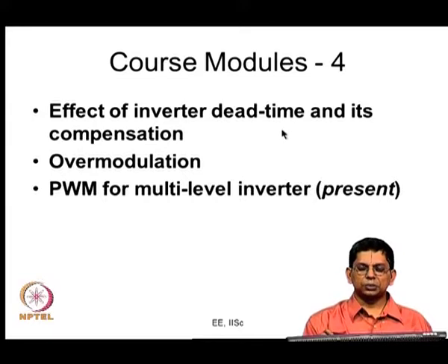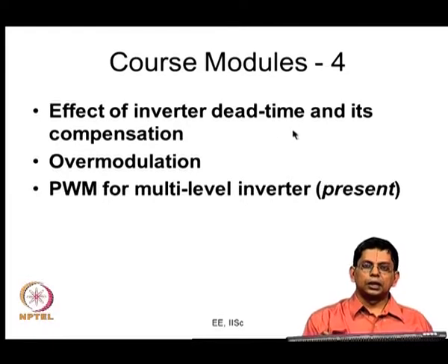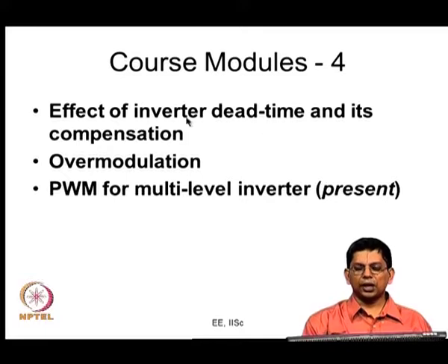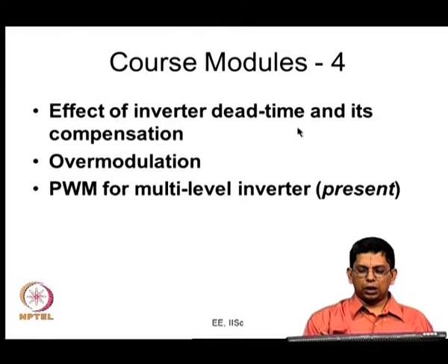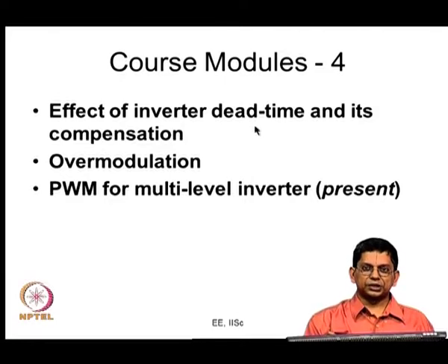After the outgoing device has been turned off, the incoming device is turned on after some time delay TD, and so that has its effect on the fundamental voltage and all that. So, a certain amount of non-linearity gets introduced here. The output is no longer proportional to the reference. Of course, the ideal output is proportional to the reference, there is a small error voltage that gets added up, and in this module we tried to see how much is that error, and that is error in the fundamental voltage, and we also tried to estimate the harmonics, etc.